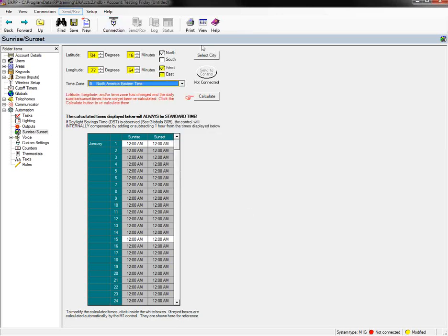So now we've moved Amy to the beach. The downside is her sunrise sunset time never changed. What you do is you have to force the software to calculate that and send it to the panel. I make a joke about this because at my own house I forgot to send the new information to the panel, and I couldn't understand why my light wasn't turning on at sunset.